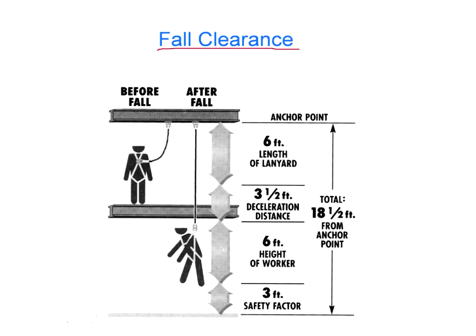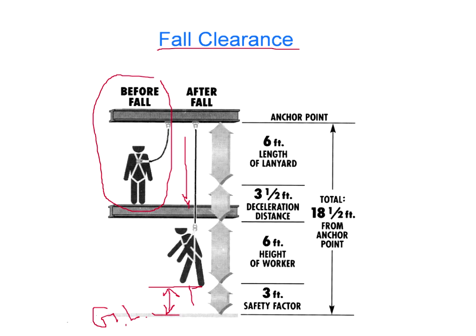And next is the fall clearance. This is very important. You see, before the fall the man is here. After the fall, you see, he is hanging. So when he is falling down, he should not touch the floor. There should be a gap. The man who is falling down should not touch the ground.